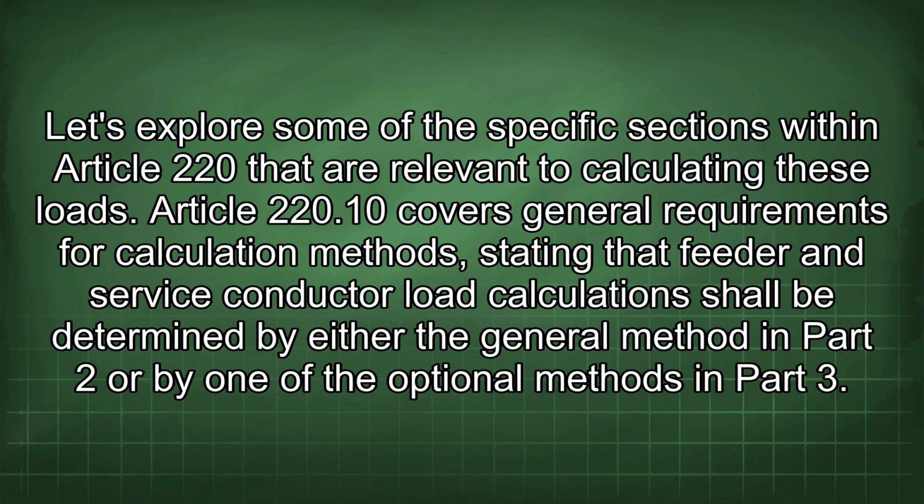Article 220.10 covers general requirements for calculation methods, stating that feeder and service conductor load calculations shall be determined by either the general method in Part 2 or by one of the optional methods in Part 3.